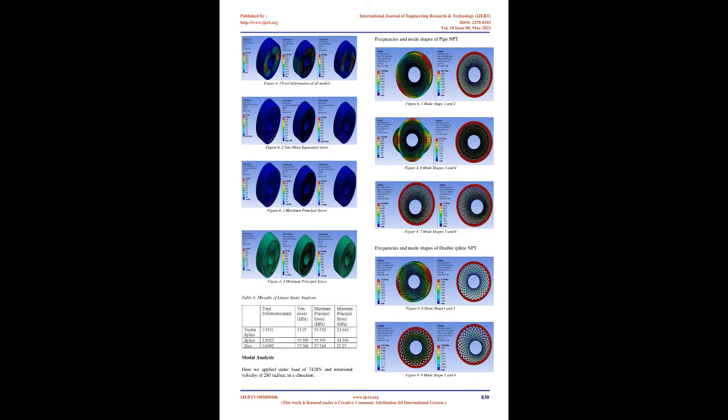Here we design 3 different spokes: pipe, spline, and double spline. As we see, the spline structured spoke is a single layered NPT, while double spline and pipe structured spokes are multi-layered NPT. The spline structure is patterned with a radius of 196.7 mm and thickness of 4 mm, in clockwise direction. The double spline is patterned with radius 196.7 mm and thickness of 4 mm in clockwise and counterclockwise directions as well. The pipe structured spokes are patterned with a radius of 10.51 mm on the first layer.